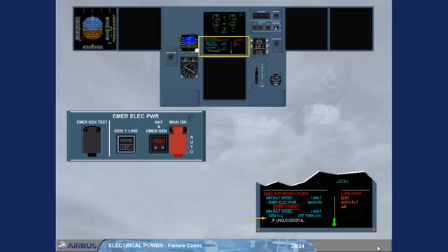Also, the engine generator resets are not successful. As the rest of the EMER CONFIG procedure has been already studied, we cleared it in order to display the next procedure. Note, if the RAT has failed to extend, the green memo, RAT OUT, will not be displayed. Also, the APU, if available, can be started, but only when the aircraft is on ground and below 100 knots.